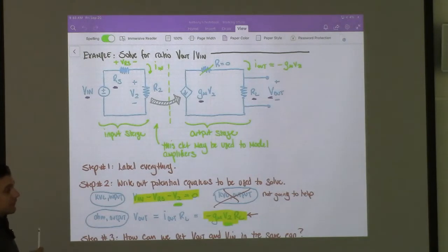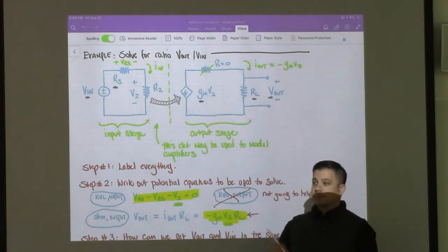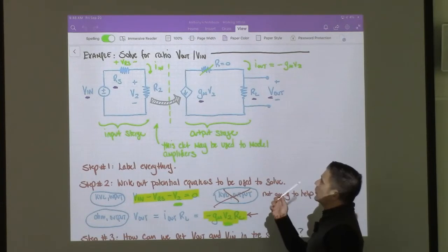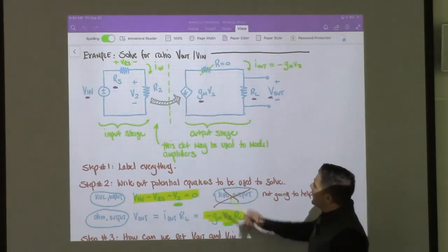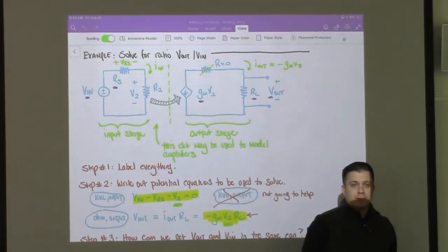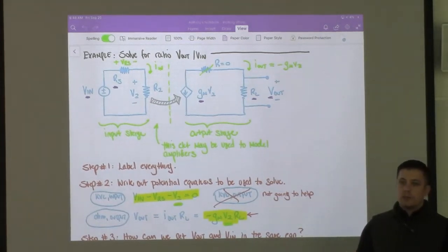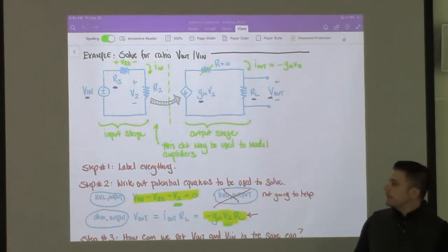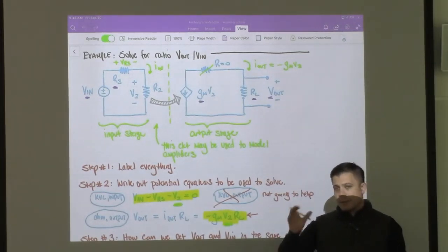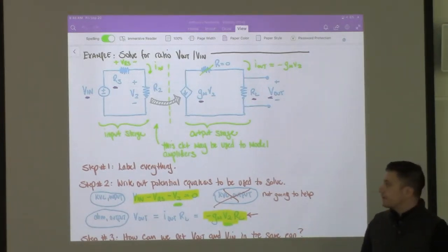Current source. Yes. You have to split up the two parts of the name in your head because they're different. So, VCCS, voltage controlled current source. And this value, we'll talk a little bit more about it later. This is called the transconductance value. And it just is a value we use to represent the ratio between voltage and a current, you know, how resistance can be used to represent the opposite relationship. It's, again, related to the G, the conductance that we talked about when we defined admittance.